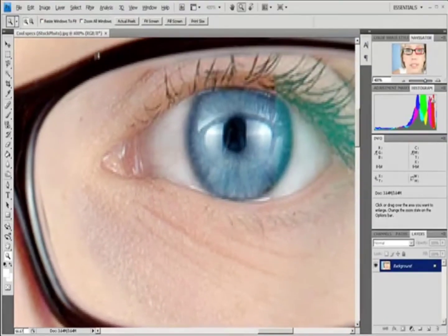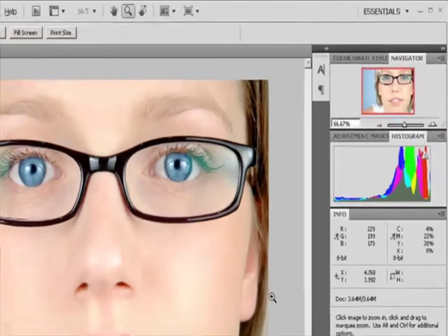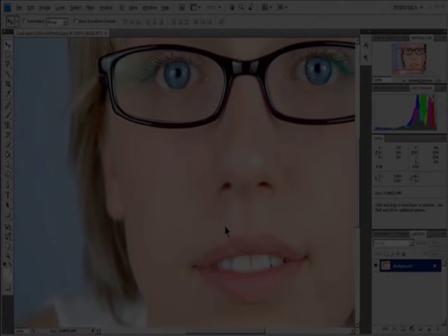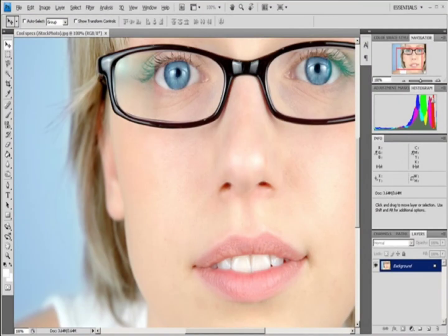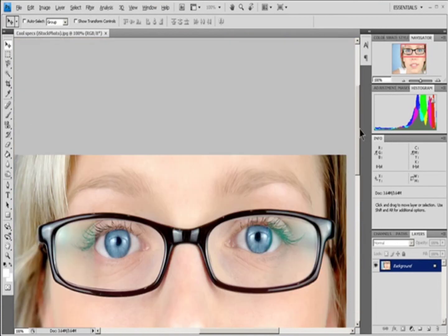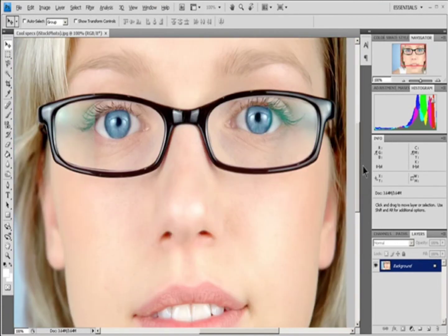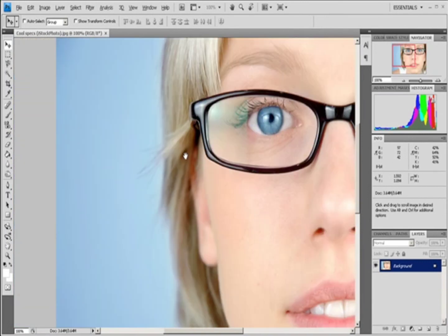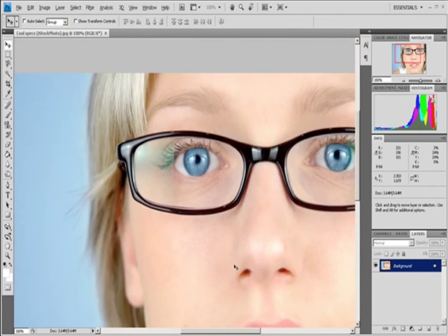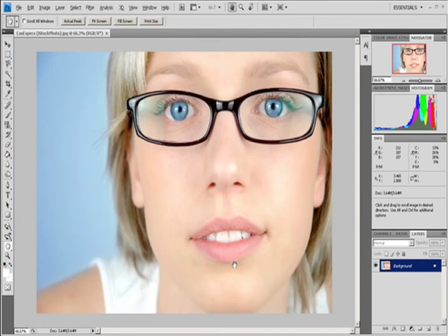Scrolling and panning. Use the Windows scroll bars. Select the Hand tool and drag to pan over the image. To use the Hand tool while another tool is selected, hold down the spacebar as you drag the image. Change pixel dimensions of an image. Changing an image's pixel dimensions affects not only its on-screen size, but also its image quality and its printed characteristics, either its printed dimensions or its image resolution.